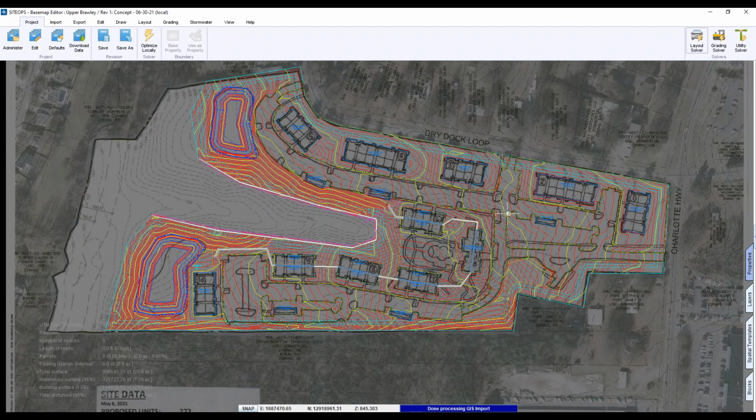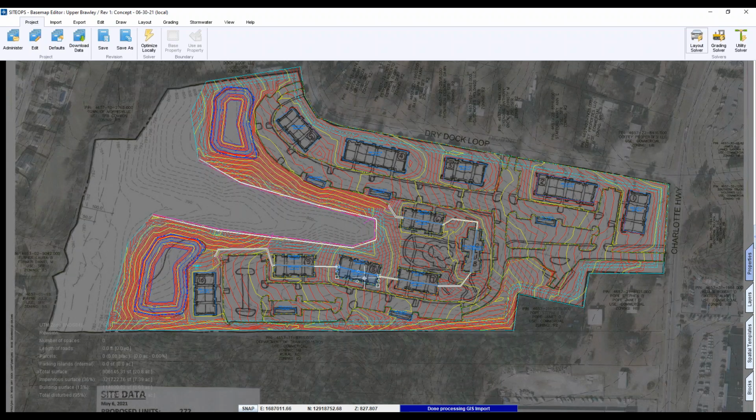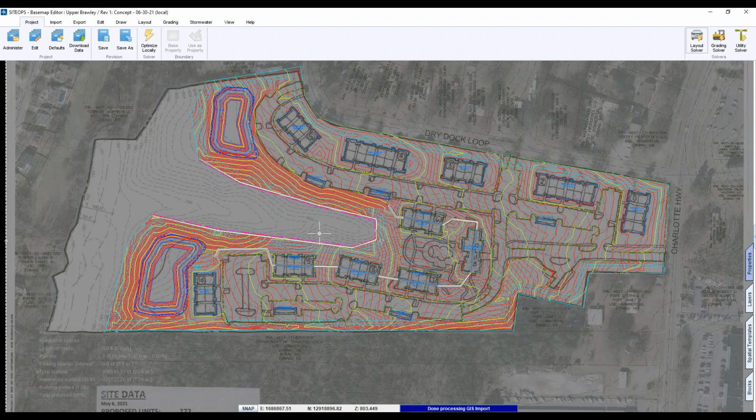So in this one, you've got all these little boxes out here as your buildings. They're all flat, except when you step one like this. So some of them they'll show, okay, we do step departments where you've got a wall that goes across that steps down a full unit level. In this case, our civil engineer will do that based on the topo he sees. So all these topo lines in here is actually his, once he pulled them off of wherever he got them. So he'll just kind of eyeball it to what makes sense with the site.